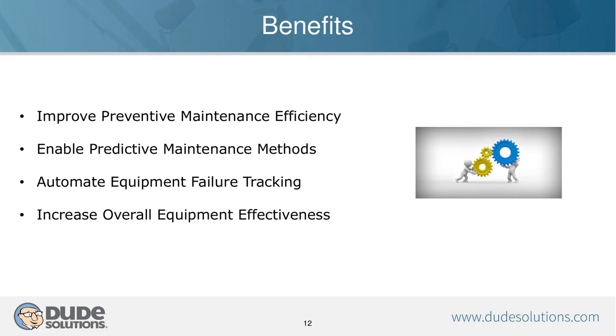So in the case of one customer that I had, we were able to implement a strategy of sending in the recordings for those cycle counts. Then we could generate work orders on that frequency. They knew that at a certain number of counts was about the time when they needed to take the mold out of service and recondition it so that they could continue to produce a high-quality product with no off-quality.